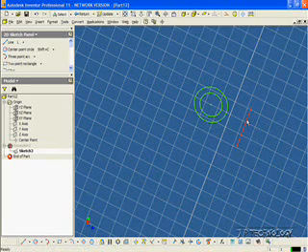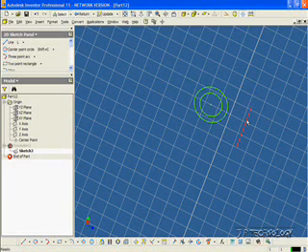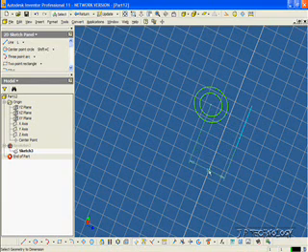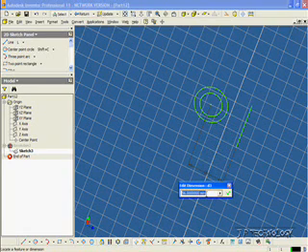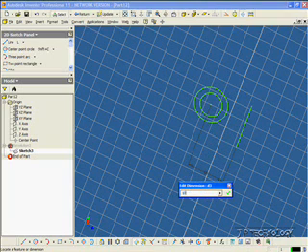To make the area that we're going around a little larger, we have to make this axis come out more. So let's click the general dimension, click the center point there, click this line. Right now it's 56 millimeters. So let's double it. Let's make it 100.